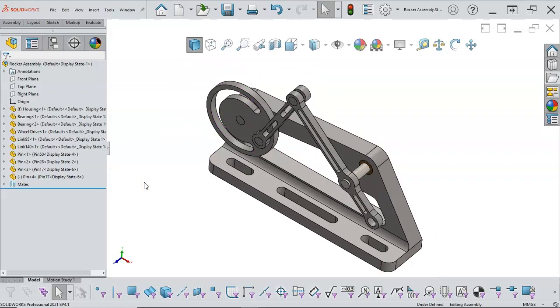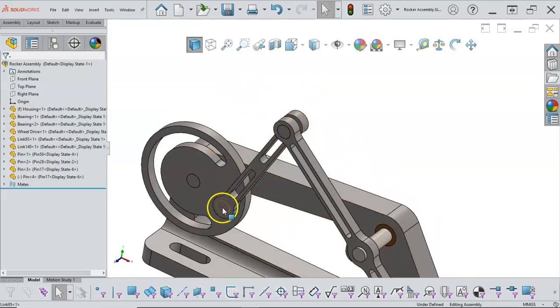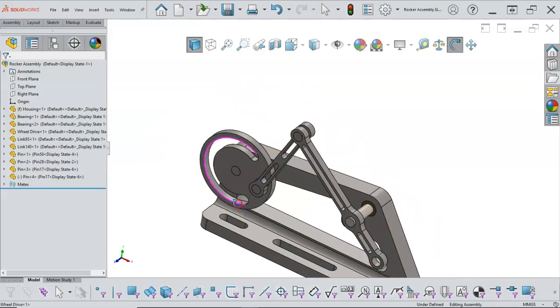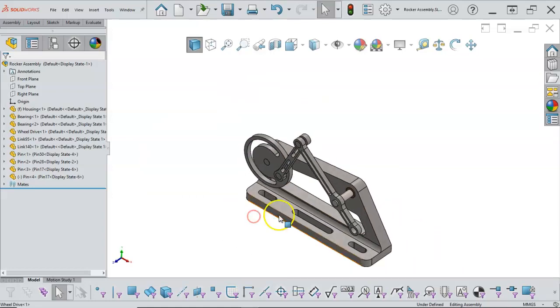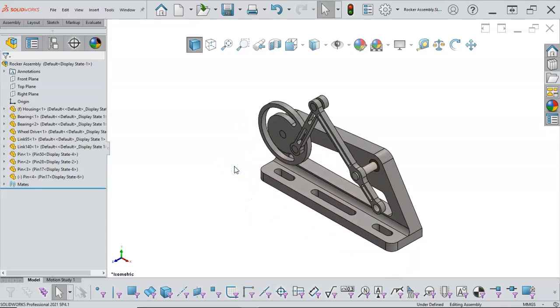So the problem there is we don't really have one side as a press fit and the other side as a bearing or bushing. And same thing here is we're riding metal to metal. As far as wear and lubrication, that's not the best way to go. So when we optimize, we'll take a look at those, and maybe it ends up with a bronze sleeve or something in there for it to ride on in these two pieces.